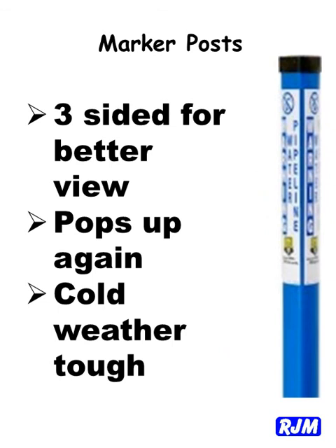If the water line is marked, it's easier to find for the next locate. Plastic pipes take longer to locate than tracer wires or metal pipes, so you can save more time by marking them after they're located. Also, there are continuous warnings that the water line is underground.